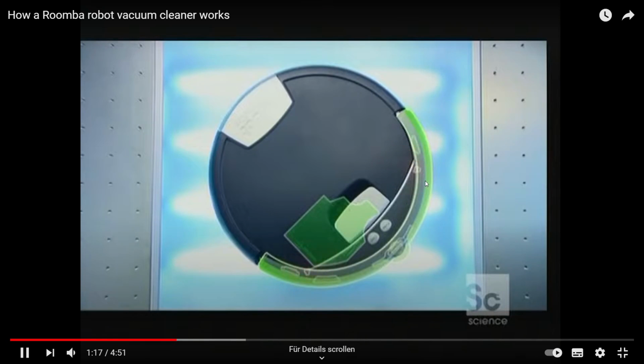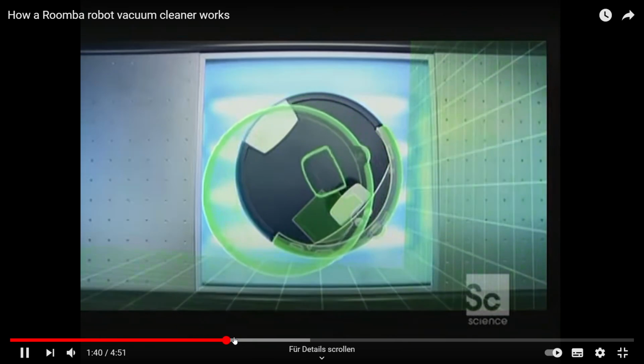So these two sensors send a signal to the printed circuit. This is the chip. These two are what I've labeled as switches. These are proximity switches which are used for the bumper. Then below that you have the infrared sensor. Afterwards, it will show you the infrared emitter and receiver. If both sensors are triggered, the robot turns and changes direction.